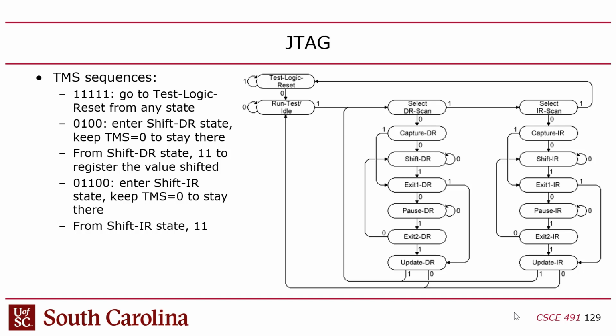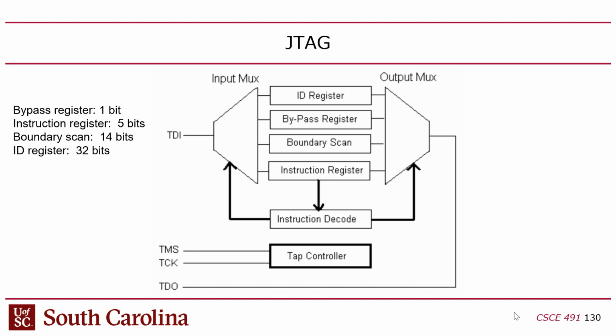Except it's not just 8 bits, it's an arbitrary number of bits, right? I'm not limited to 8-bit exchanges like SPI is. These things can be millions of bits, which they are on the FPGA. In the case of the FPGA, they're millions of bits I'm shifting here. Okay, so there's a few specific instruction